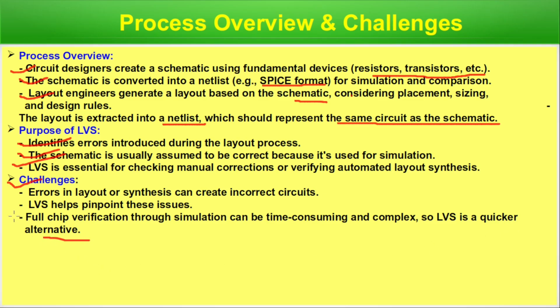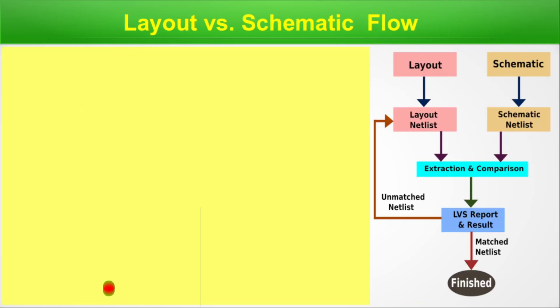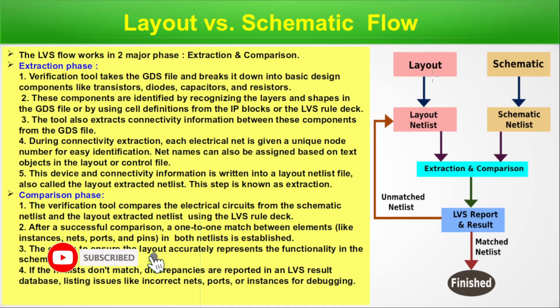Full chip verification is a step that gets done post simulation. So we are done with this slide. We will move to the next slide. Now layout versus schematic. This is the layout, and the netlist expected from that. This is the schematic netlist, then extraction and comparison, the LVS report and analysis of the result. If the netlists match, then we are finished.